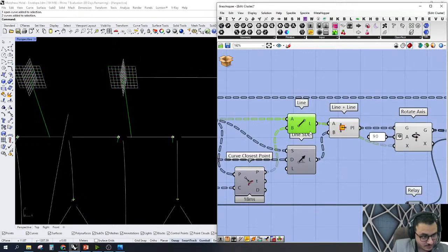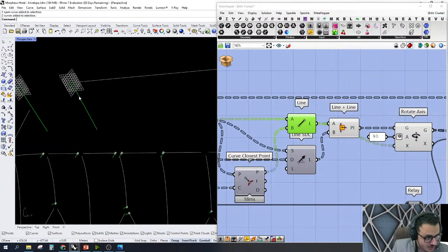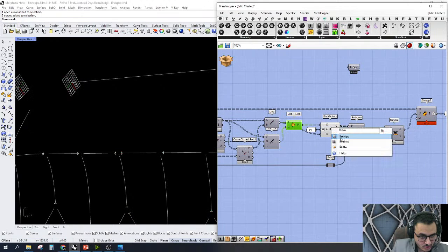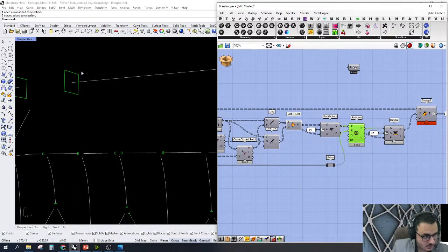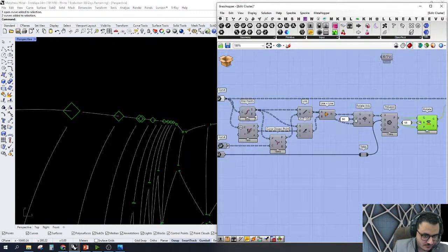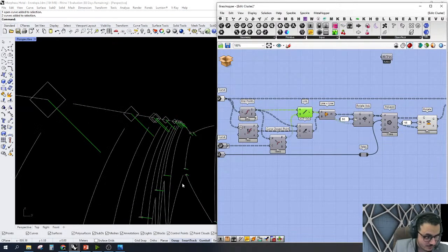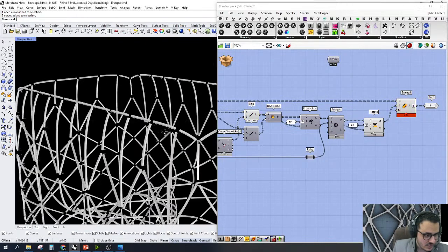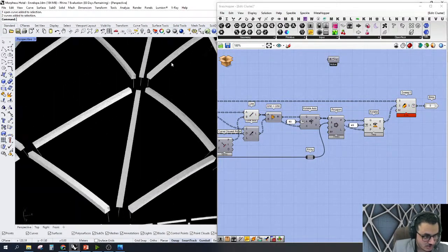The axis is this curve, which I used to create the plane in the first place, and I created, let's say, the section for the structure. In this case, I created a simple section, and again I just rotated it 45 degrees because I wanted it to be exactly pointed to the main surface. And of course the sweep after that, and this is exactly the structure.